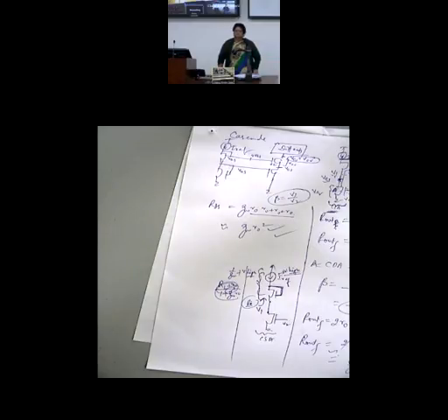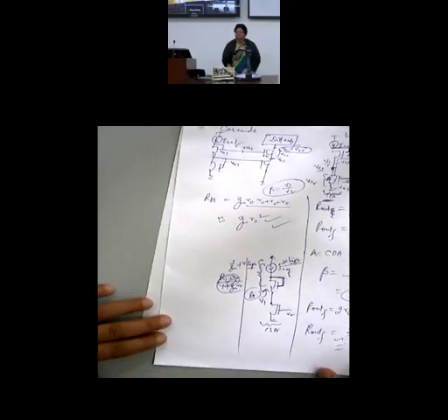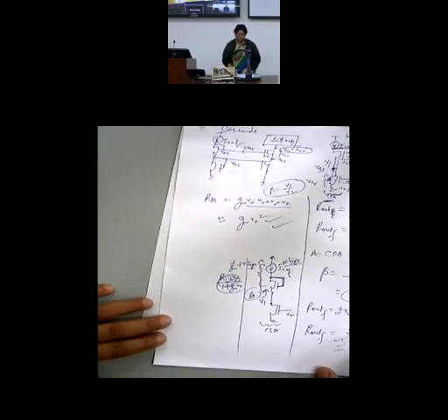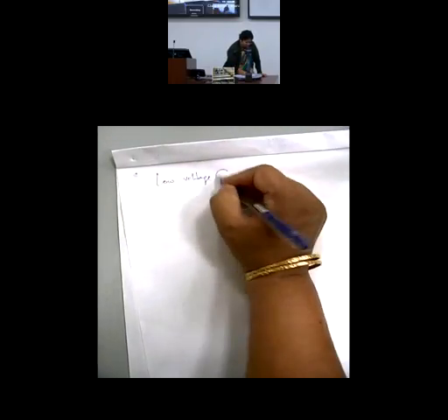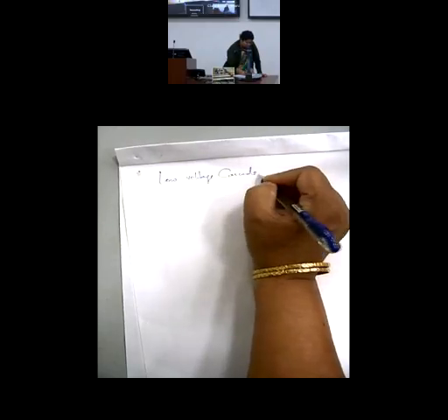Fine? So we see that Cascode and Wilson give us the same performance. So we get roughly the same RSS and we receive roughly the same voltage headroom. If I want to have an even higher RSS and even lower voltage headroom, what should I do? So here we have a low voltage cascode connection. That is, cascode is modified.